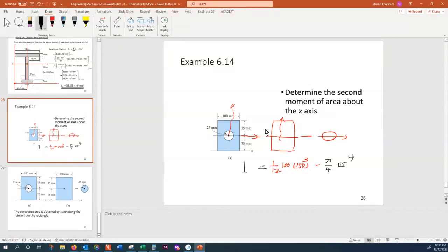For second moment of inertia, we introduced the calculations for primitive shapes like rectangle, triangle, circle. And then we went into the compound shape, how this can be broken into primitive shapes. And if the standard value from the table is different from that of the compound shape, you have to calculate a penalty. To calculate the penalty, you go through the parallel axis theorem. And we did some examples of that.